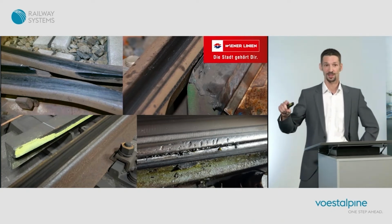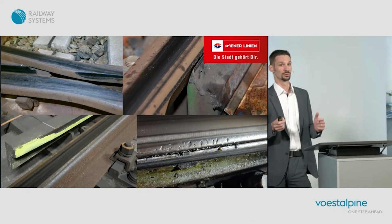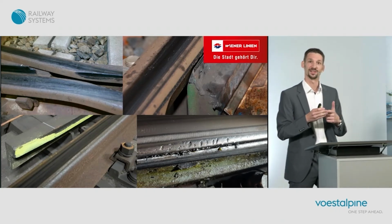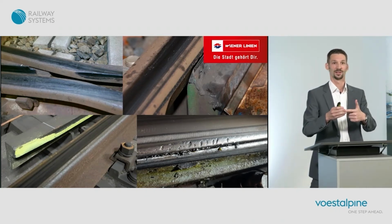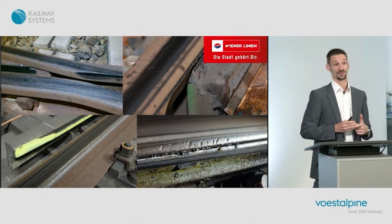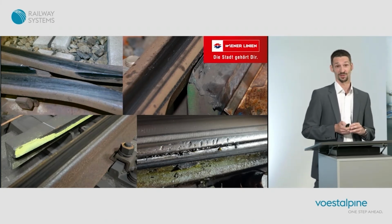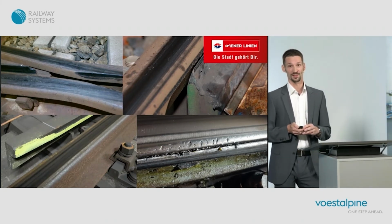We sprayed color upon the check rail in order to derive the first point of contact. And the closer this first point of contact comes to the very entrance of the check rail, the more dangerous it can get. And if it's too close, you also have to introduce a speed limit on this switch.